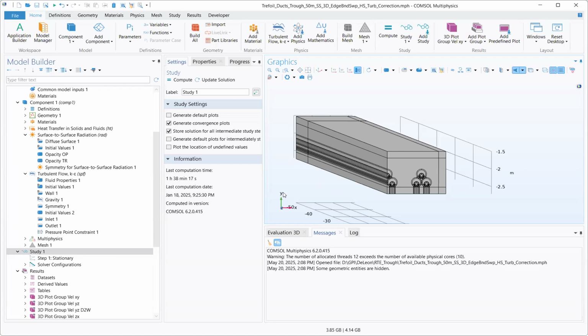If we start the model from ambient temperature, then we're forcing the solver to try to solve the model with no help, starting from ambient. But if we give it an initial value, a good educated guess that's close and reasonable, then you could solve quicker. But that's the only thermal, that's electromagnetics as well, right?